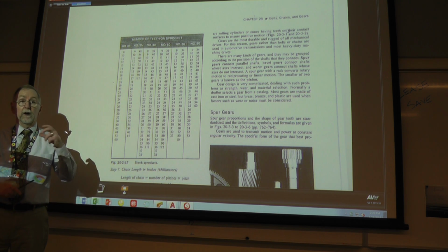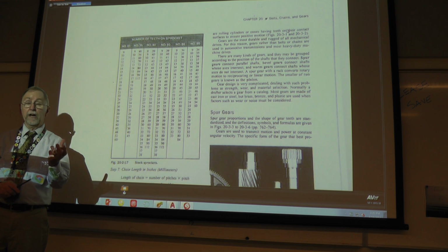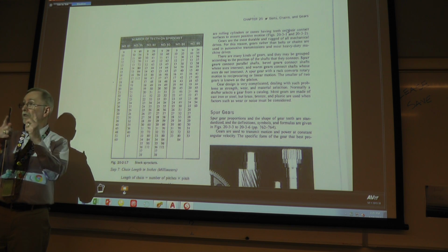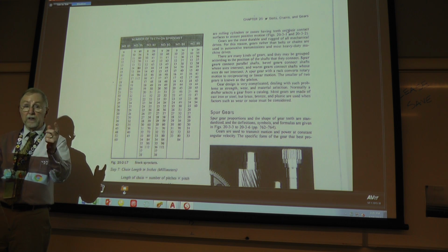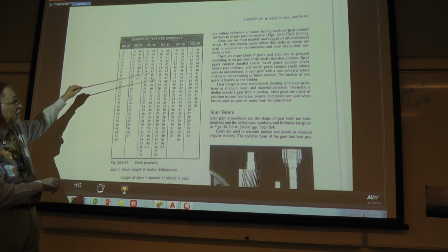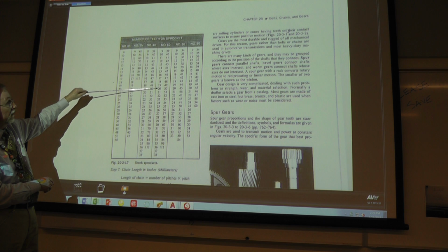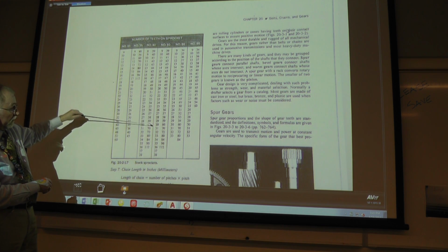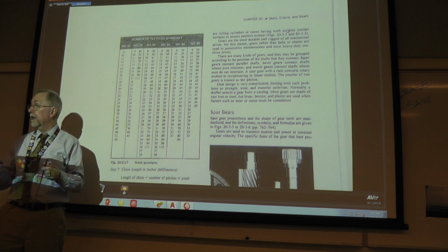So sometimes I run a design calculation that comes up with a certain combination of teeth, 20 and 30, let's say. So I go in and I look on my particular chain, like at number 50, okay, there's a 20 that's available, and there's a 30 that's available, so I can use that in my design.